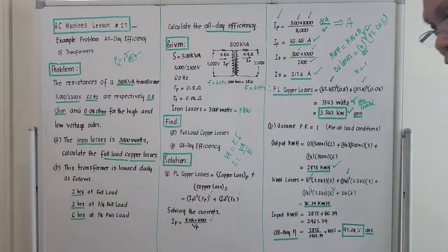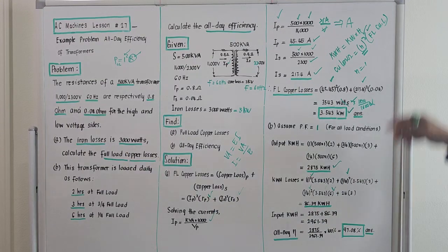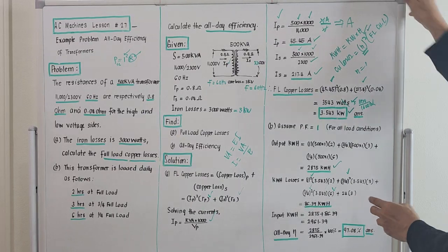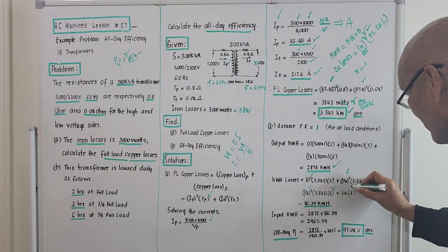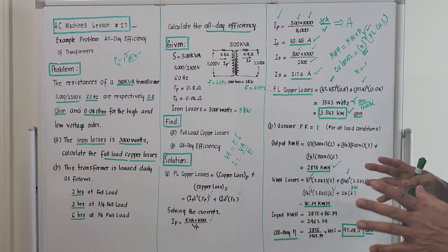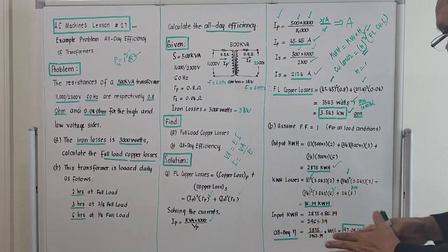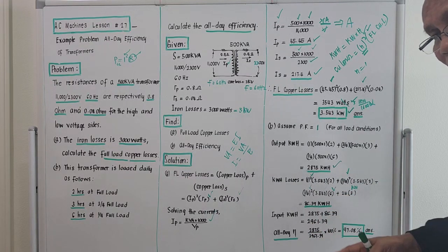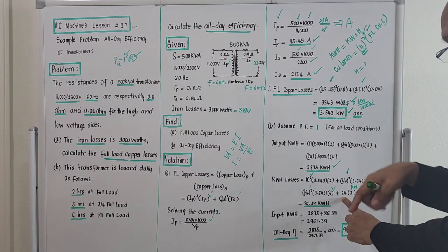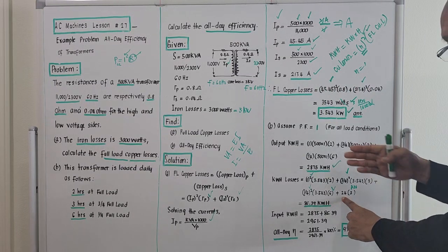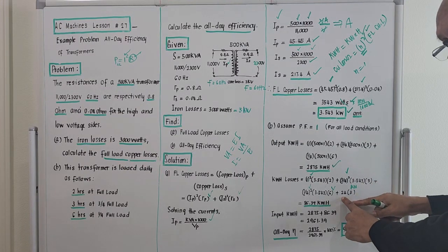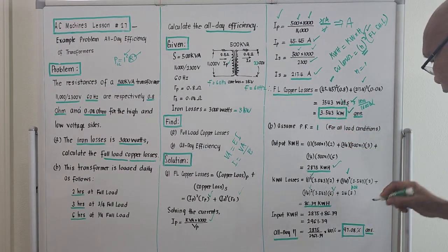What's the last part of the losses? It's the core loss. Core loss is actually 3K, 3,000 watts, so this is 3 kilowatts, right? For the core loss, whether the transformer is with load or with no load, the core loss is actually present, so the multiplier should be 24. It is present for 24 hours. If there is no load, there is a core loss. If there is load, there is still a core loss. So this core loss is present for a total time of 24 hours.